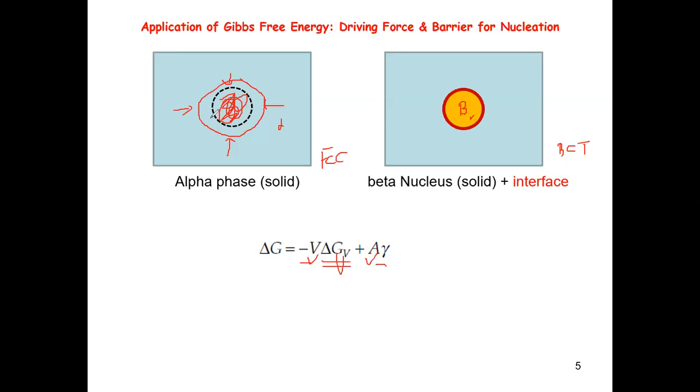So the constraint can only come from the nearby beta or the nearby alpha phase. The beta phase is then going to try to expand and push onto the alpha phase. This basically means that in the local region of this alpha-beta interface, the alpha phase is compressed, right? And the beta phase is also compressed because I have to squeeze. Does that make sense to everyone?